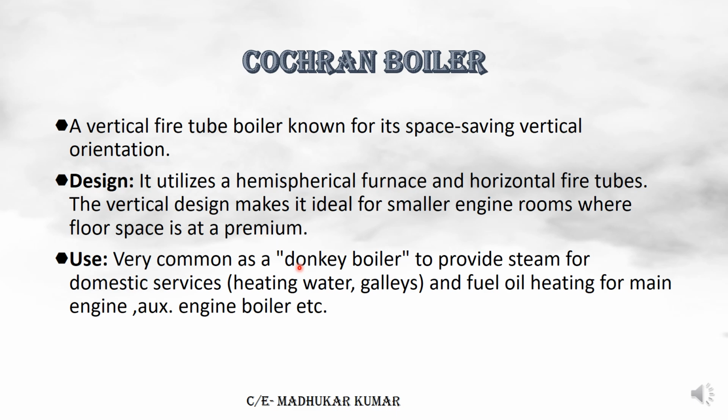It is also known as the donkey boiler. It is a very famous word, so any marine engineer will know this one, donkey boiler. It basically provides steam for domestic services like heating water and supplying the galley, as well as for the engine room. Fuel oil heating for the main engine is also done using it. So this is utilized whether the main engine is running or not running.